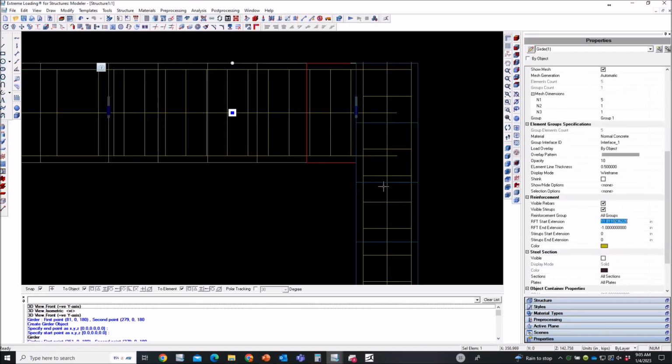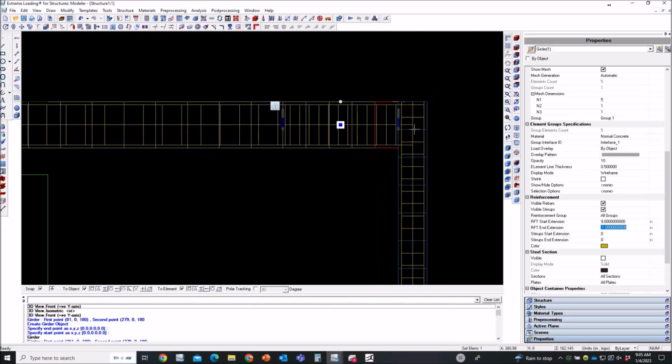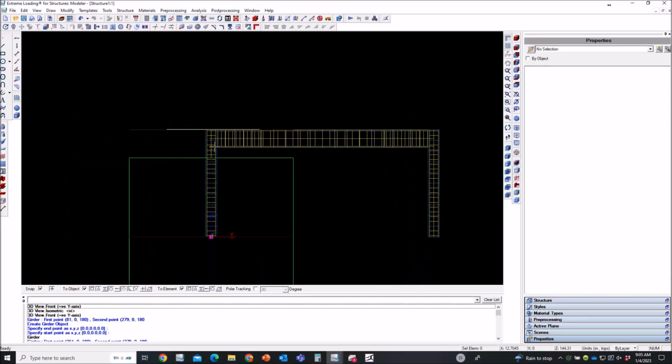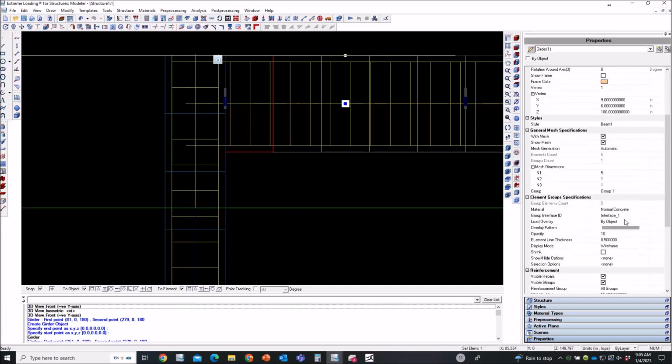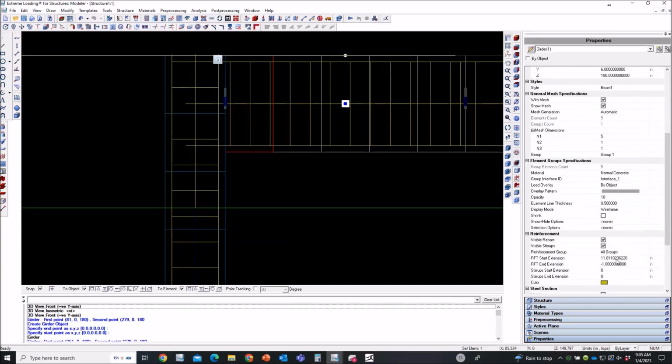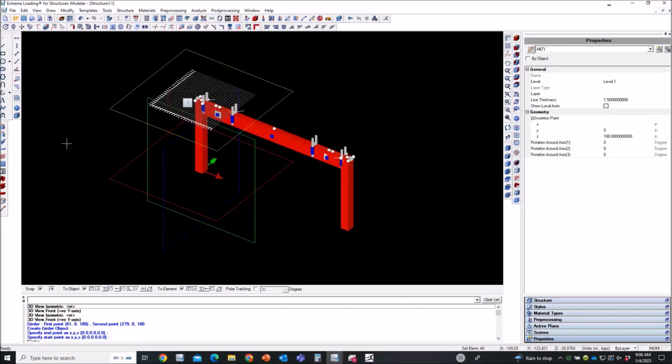If I have this column as 18 inches, so 9-inch will be enough from here. And then when I copy this beam to the other side or mirror it, then we will have also an extension of 9 inches, as we are going to show later on. For the one in the end in here, I need it to be all the way to the end. So I'm just going to select this beam and change here the reinforcement rebar extension at the start to be 18 inches.